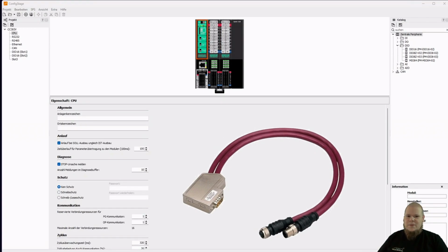We have also collected the more frequent error sources for the Profibus. If you don't use the connection adapter, but connect the cable yourself, then you really have to check the wiring. It has already happened that a customer has mixed up the P and the N wire at the Profibus connection and has searched for it for a very long time.